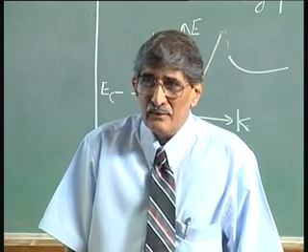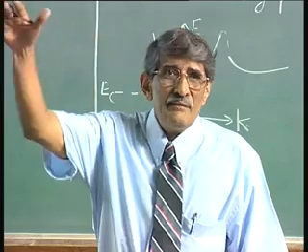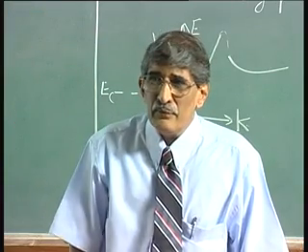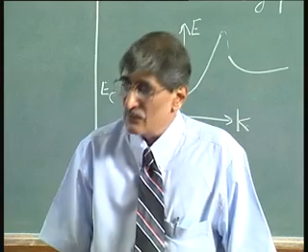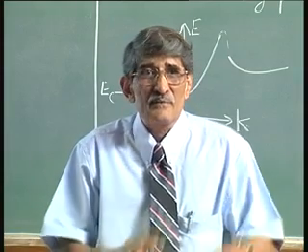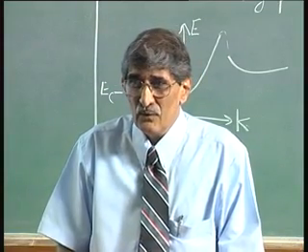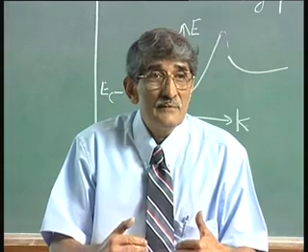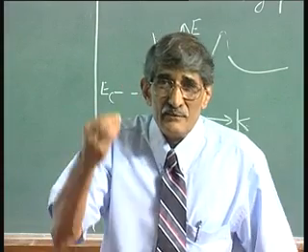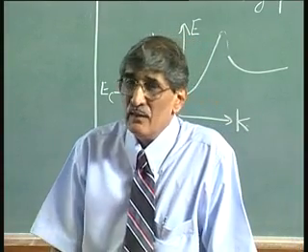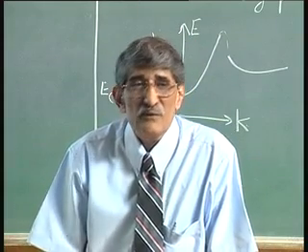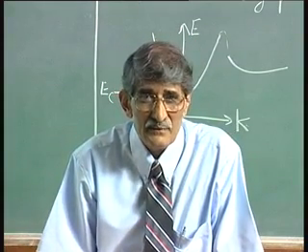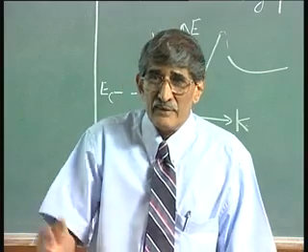Okay? It is like pouring few drops of water into ocean. It is not seen. So it's exactly that thing that is happening. 10 to the power 17 and 10 to the power 15. So that means you add 10 to the power 15 p-type dopants and 10 to the power 16 n-type dopants, it does not make a junction because you have got high concentration of electrons and holes. How can you make this device work as a p-n junction?